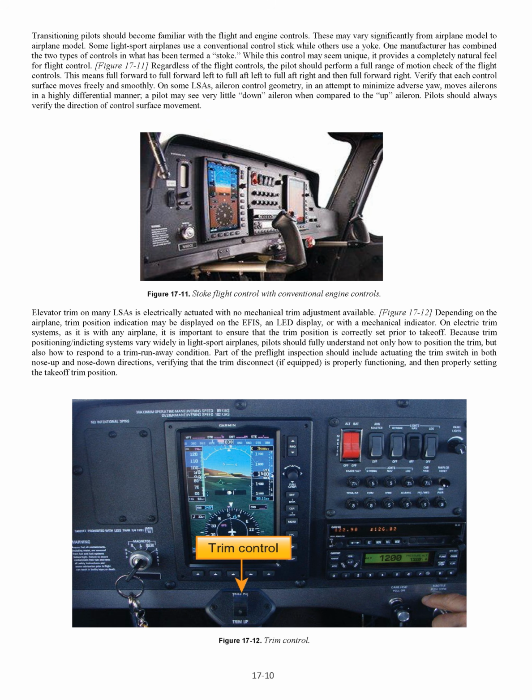On some LSAs, aileron control geometry, in an attempt to minimize adverse yaw, moves ailerons in a highly differential manner. A pilot may see very little down aileron when compared to the up aileron. Pilots should always verify the direction of control surface movement. Elevator trim on many LSAs is electrically actuated with no mechanical trim adjustment available. Depending on the airplane, trim position indication may be displayed on the EFIS, an LED display, or with a mechanical indicator. On electric trim systems, as it is with any airplane, it is important to ensure that the trim position is correctly set prior to takeoff.